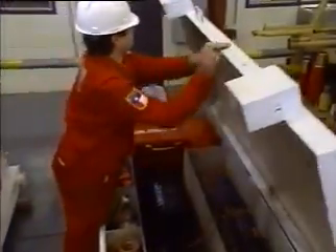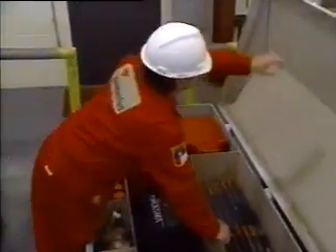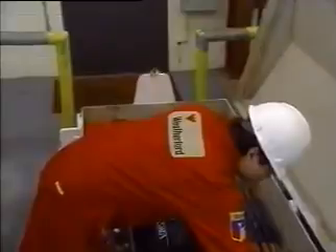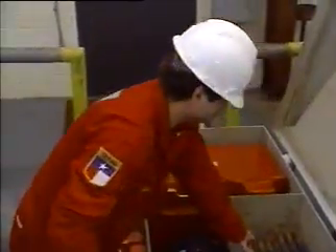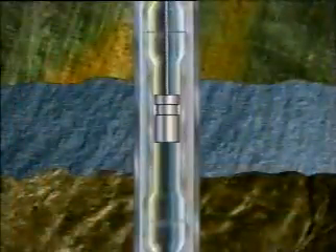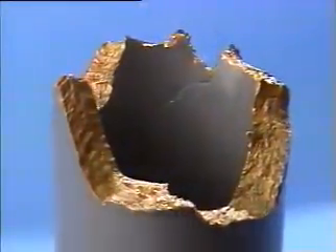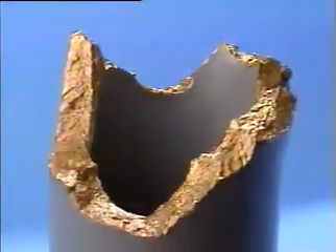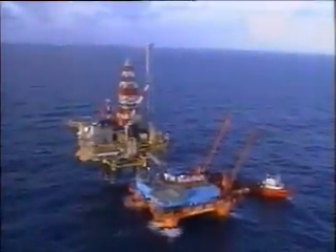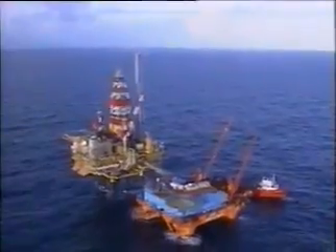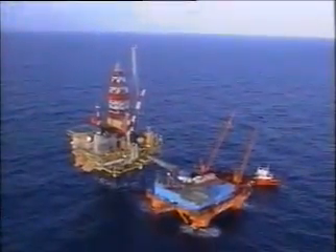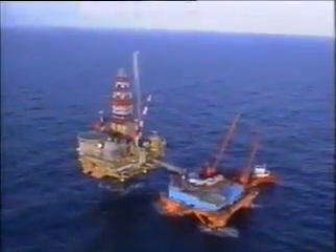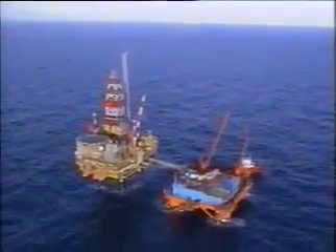Still another tool used in fishing is the severing tool. The severing tool utilizes a powerful explosive charge run on wire line which violently severs drill pipe, heavyweight drill pipe, and drill collars when conventional back-off techniques are not possible. The severing tool is recommended only as a last resort in expensive open-hole situations, such as offshore drilling operations.